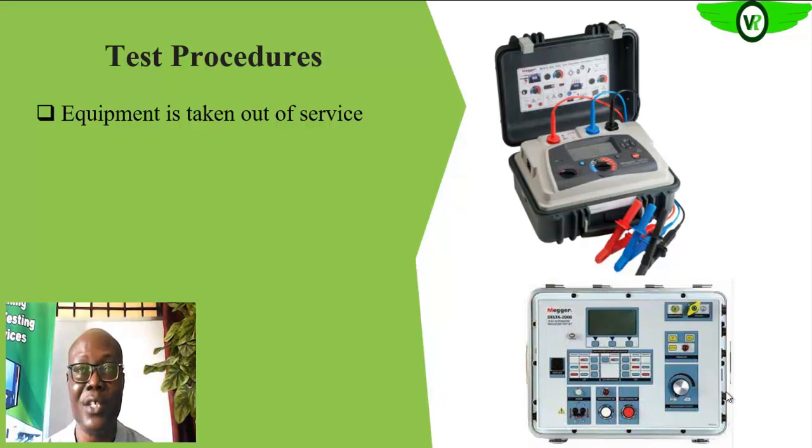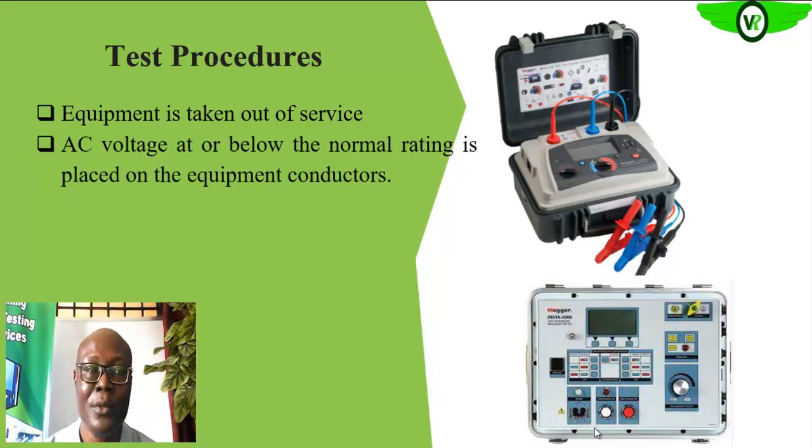That means after isolation, we need to test if there is voltage, and then discharge whatever charges may be there. We discharge the equipment, since we are dealing with medium voltage and high voltage equipment. So we'll make it safe for our test after isolation.